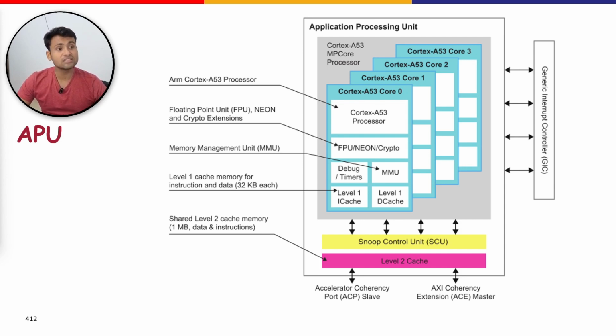The single instruction multiple data also supports the Neon processor to operate on the elements of two input vectors to produce a corresponding output vector. One instruction is used to configure the Neon processor to perform the same operation on multiple data elements of the same type and size. Talking a little bit about the crypto core, it is a dedicated encryption decryption tool which supports again SIMD instruction sets.